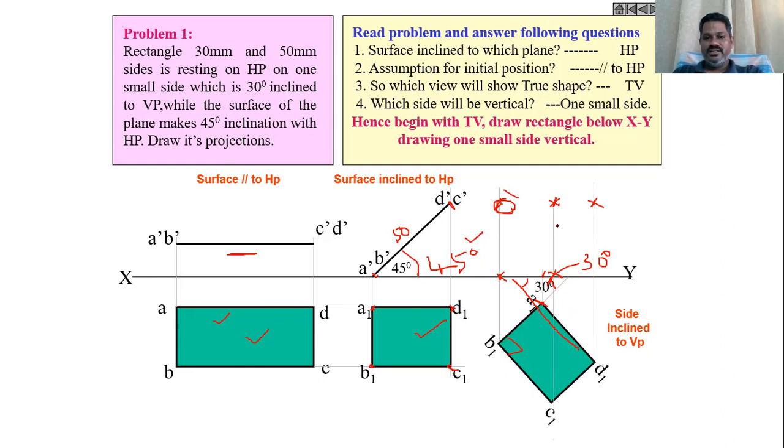The top view of the third step and the front view of the second step are projected to get the intersection points, and those intersection points are used to draw the front view when the edge is making some angle with the vertical plane. This is how we obtained the points, then join all those points to get the shape.